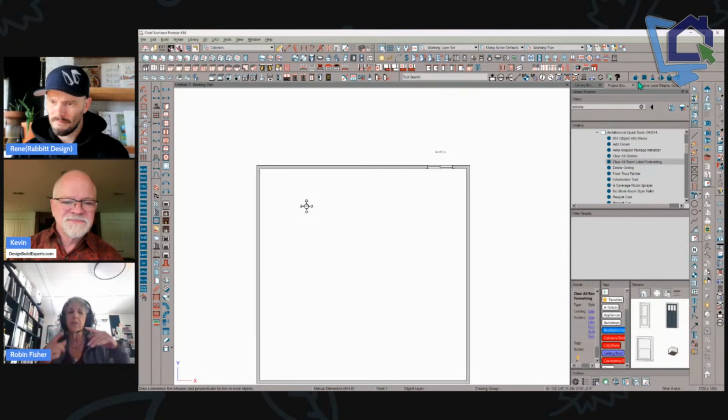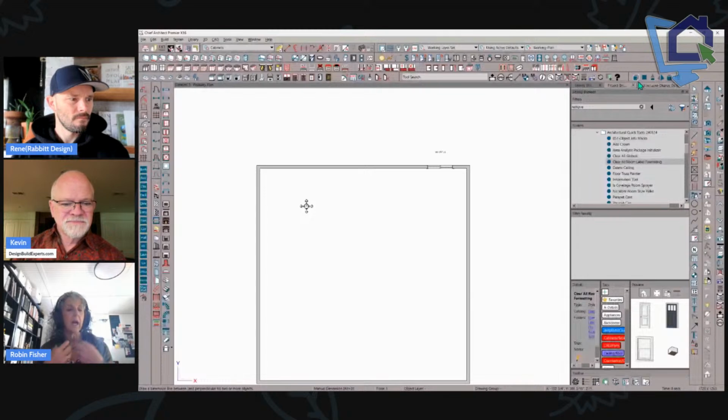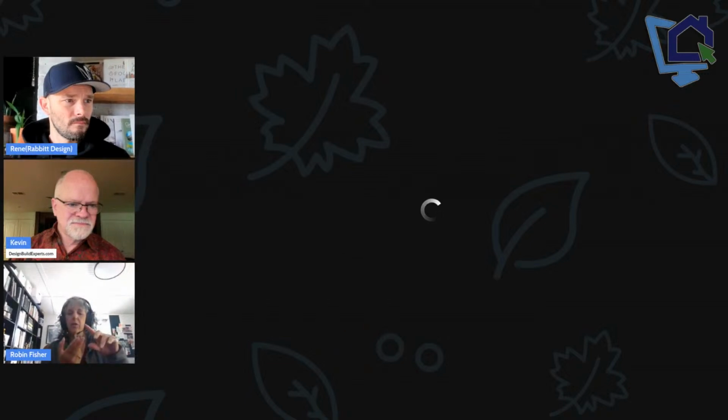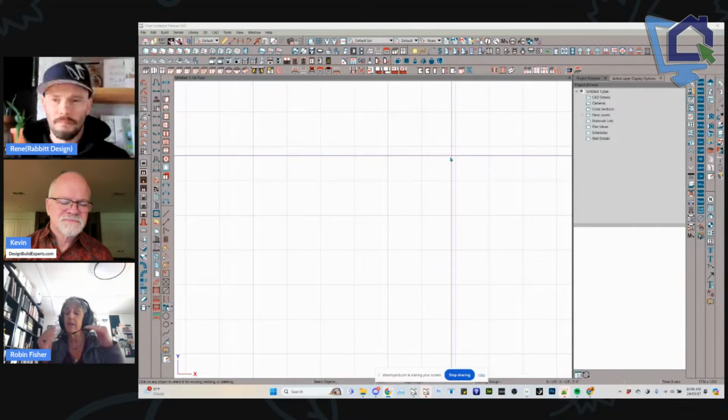The next thing that I do is I use my manual dimensions, and I only have this attached to my windows. How do I want to do it? I measure to the sides of the windows. Some designers measure to the casings of the windows. Where do you want it to attach? Then I do not use manual to connect to cabinetry at all. So it's really just openings and the obstacles, right? So it's just windows, doors, those type of things. So that's all I have it set to.